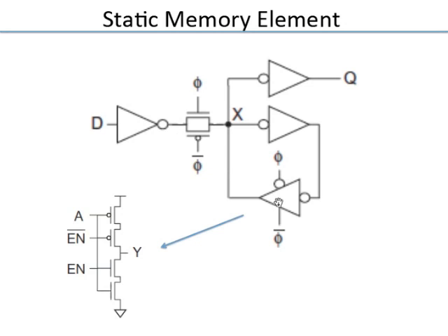What this tri-state inverter does is that you operate the tri-state inverter with the opposite polarity to this transmission gate. You only want one person to drive that node X, so that there is no fight. So when you want to write data into the X, you disconnect or you make this transmission gate into high impedance. So when you turn this transmission gate on, these two are made off. How? Just by connecting the appropriate polarity.